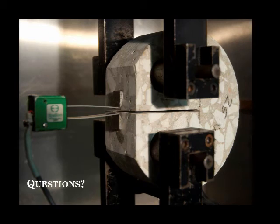Yeah, I think his point is valid, that the fracture energy would be slightly different, but not the K1C. Correct? Well, theoretically, K1C is a material property. Yeah, I'm saying that the ratio of load and CMOD won't be affected, but the total fracture energy would be affected by how you measure the displacement. Well, that's a good point.